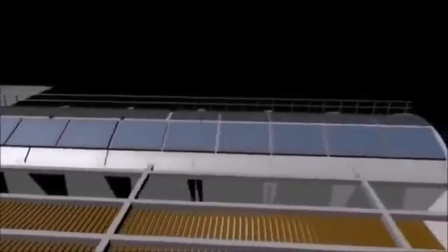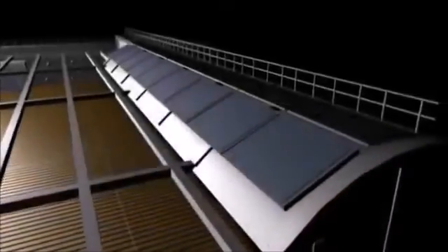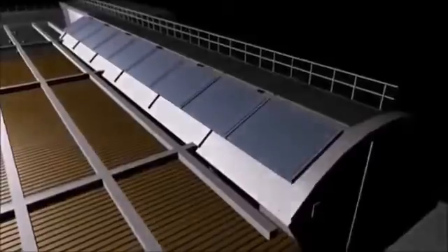The building was constructed using an approximate total of 6,000 metres cubed of green concrete. The review of the design amassed a total of 80 out of the possible 140 points, with green concrete contributing up to 2 out of the 3 possible concrete points for the materials section. The building boasts an 85% reduction in electricity consumption compared to the existing council house of similar size, a strong statistic comprised by the strong contributing effect of green concrete.